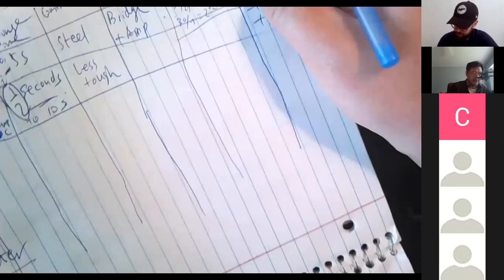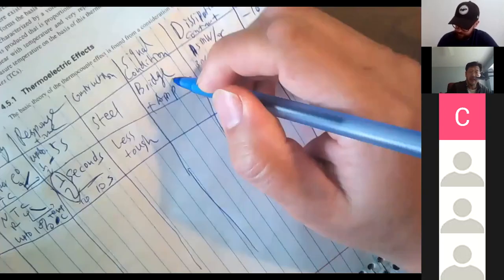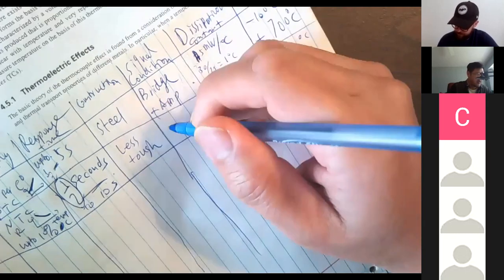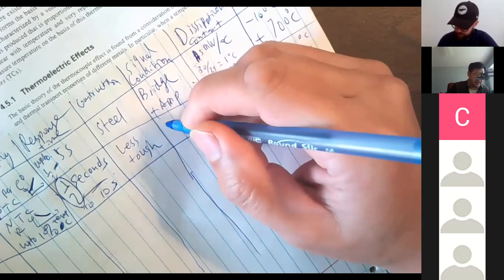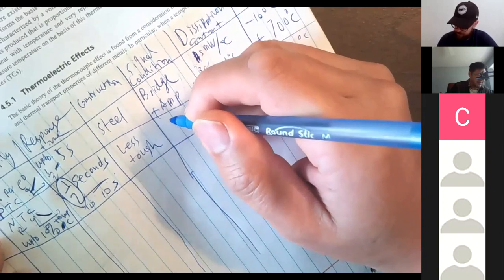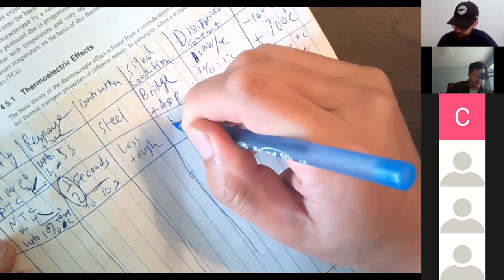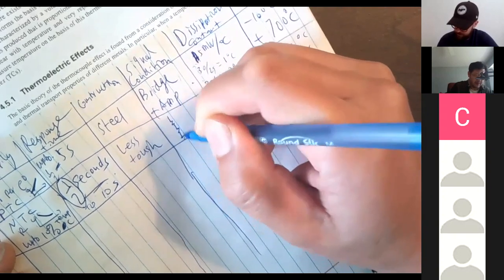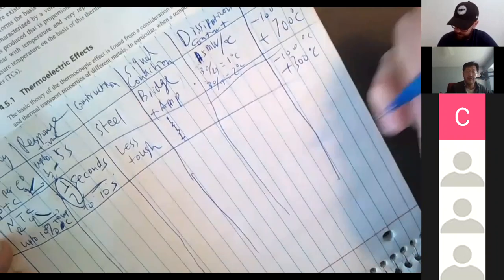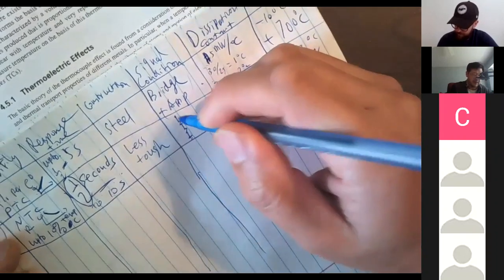Signal conditioning can be the same as previous. Actually, you can save a bit of money by only using one resistor. That means use this. So only use two resistors instead of a bridge.